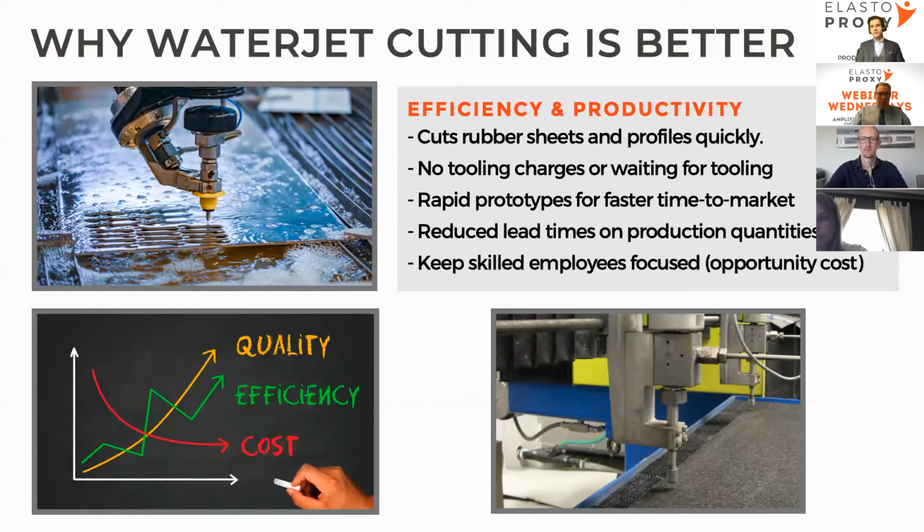So the lead time is less, again, depending what it is that you're cutting and how quickly you need to cut. The other advantage with WATERJET cutting versus die cutting is also that 90-degree corner. Die cutting has a hard time coming up with that finished sharp edge. Most of the time the corners are slightly rounded. So if you need sharp edges or detailed cuts to be done, WATERJET cutting is the best way to go.